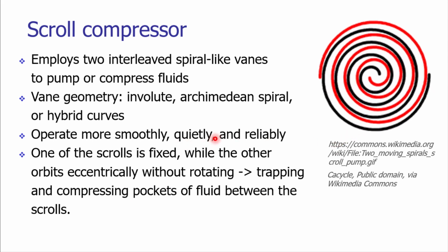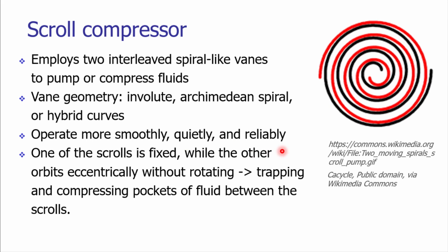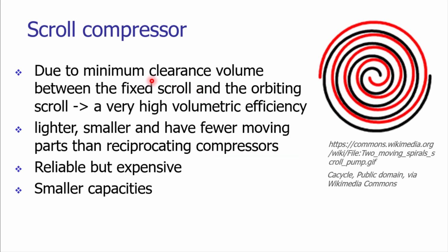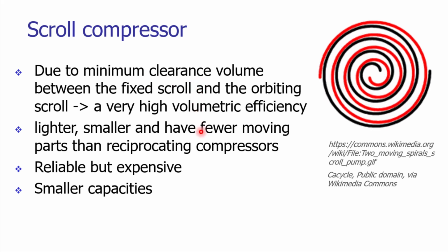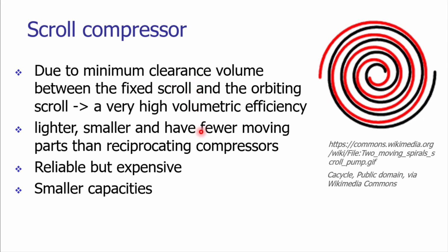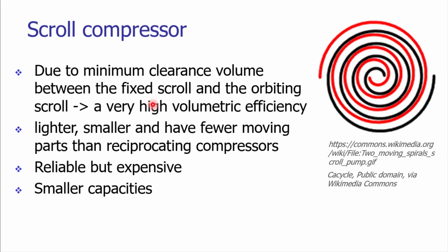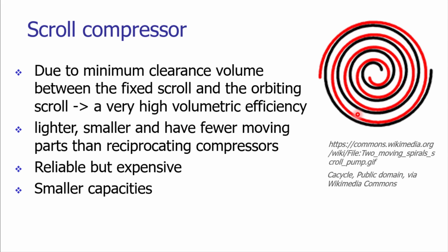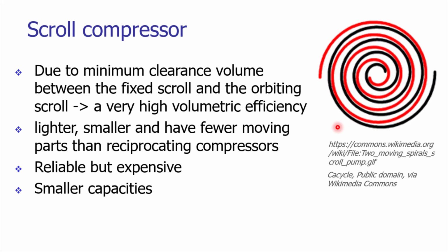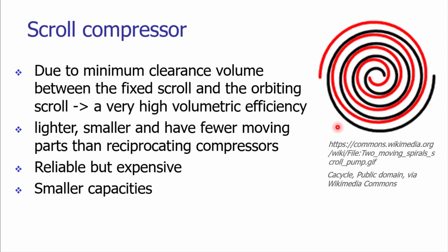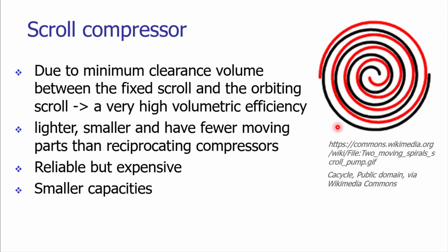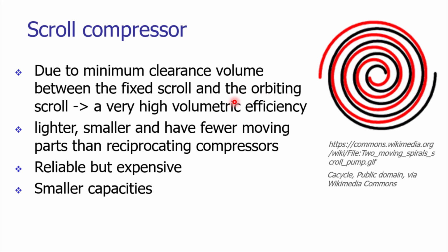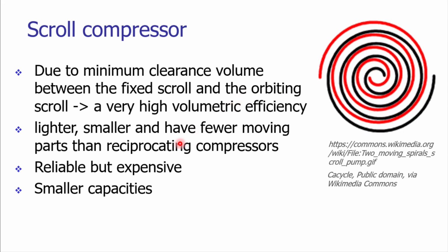The operation of the scroll compressor is smooth and quiet, and its reliability is quite high. Due to the very small clearance volume between the fixed scroll and the orbiting scroll, scroll compressors offer high volumetric efficiency. As the clearance is less, the leakage is less, therefore the volumetric efficiency of the scroll compressor is quite high.